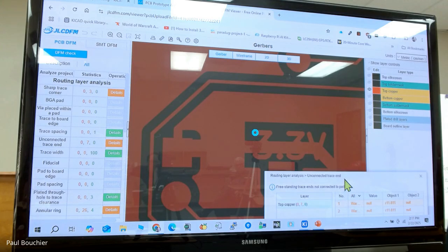And why 3.3 volt would be in copper, whoever put it on there must have been messing around. Anyway, the important thing is, why didn't the DRC catch that? All those edge layers, edge patterns, I find they don't do what this one does. This one shows you where it is, whereas in KiCad they just list an error and you wonder what it means. I wouldn't be surprised if this is part of the reason why you've got all those errors.